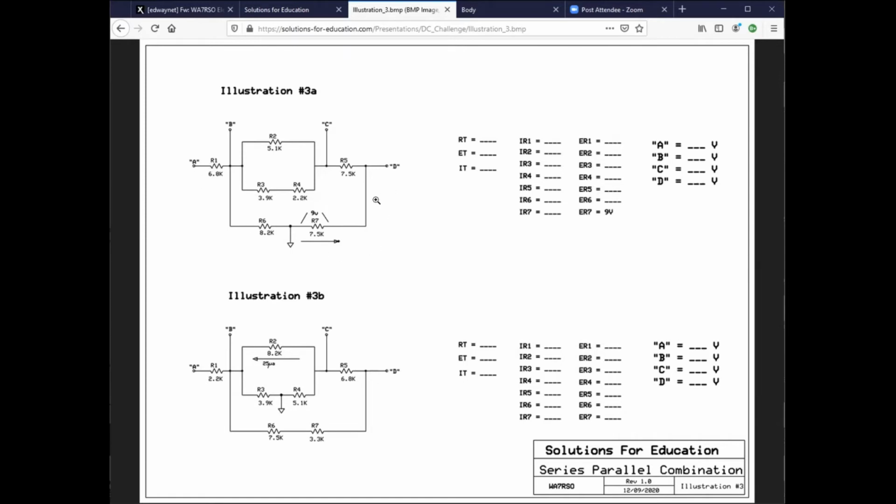So guess what I'm doing right now with my poor students? I am flipping their mind back and forth between parallel one time, serial another time, back and forth, back and forth. Not only that, but somewhere in here, they have to worry about potentials and they have to worry about IR drops. Remember, an IR drop here is an IR drop of 9 volts. Why is it IR drop? I thought you said that was 9 volts. Yes, because this 9 volts is because of current times resistance, according to the formula, that pi symbol we give them, okay? So you say, oh, that means then if I know this is 9 volts and 7.5K, that means I got a little bit more than 1 milliamp flowing through that resistor.